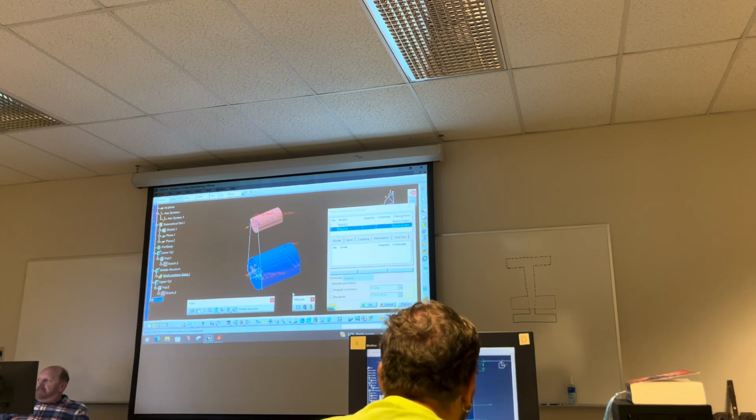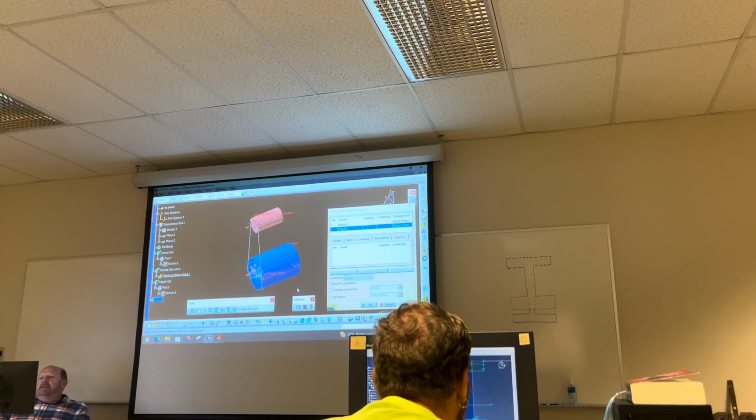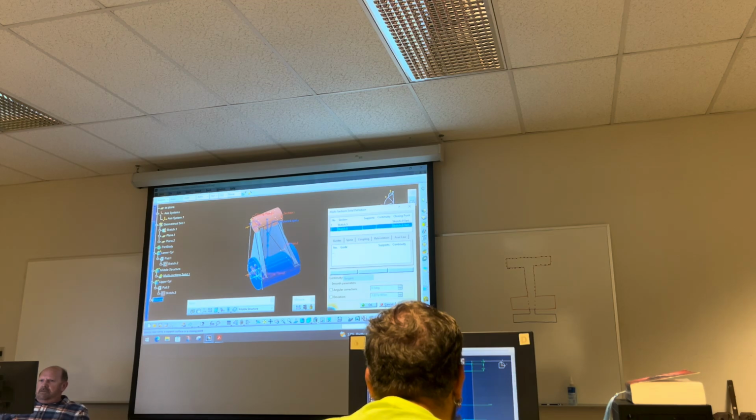I'm done with this, but I'm going to preview it, and the reason is the closing points. You usually want those to line up, because when they don't, the solid will twist. Since I have closing points on opposing corners, let me show you what happens. So there it is, it's twisted.